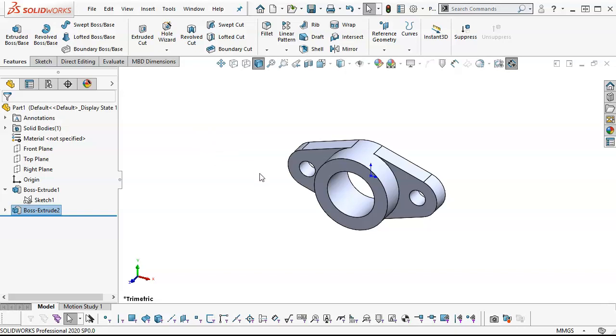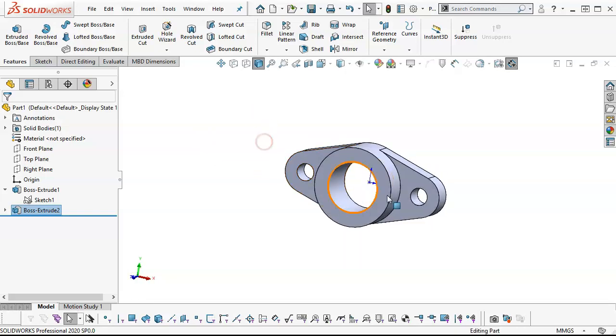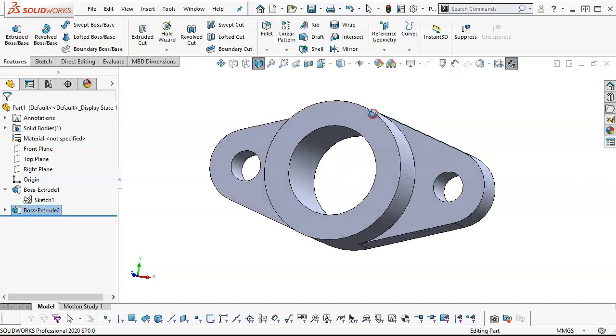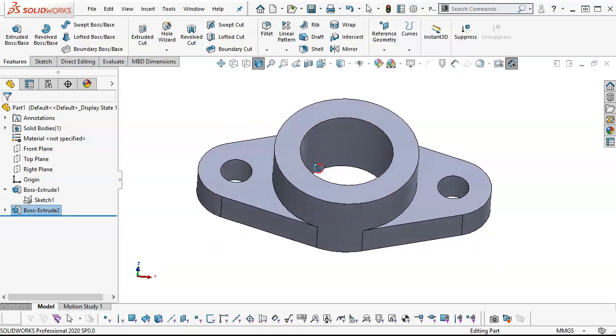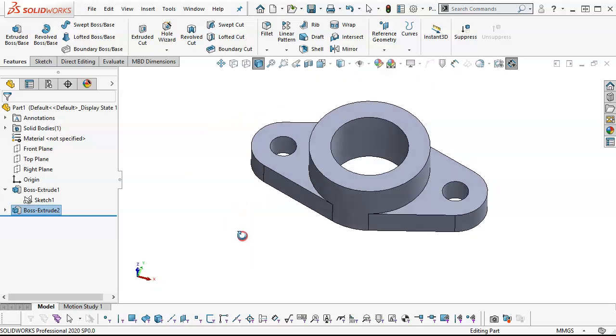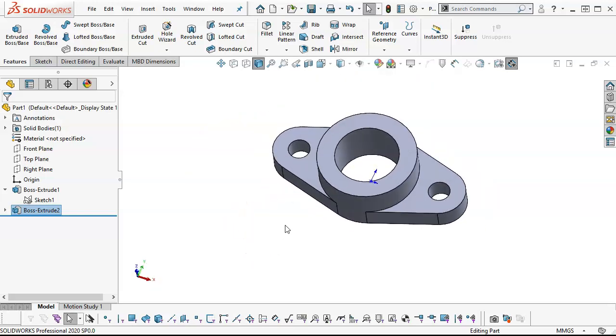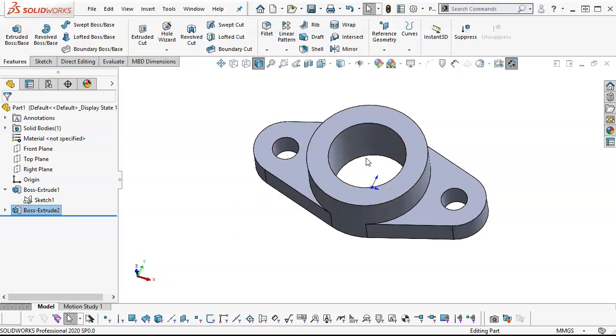Question is the fillets from a manufacturing standpoint. Most of these parts were designed and intended for a casting process. So the fillets were necessary as part of the mold. It was hard to keep the sharps in a sand casting or other casting processes.